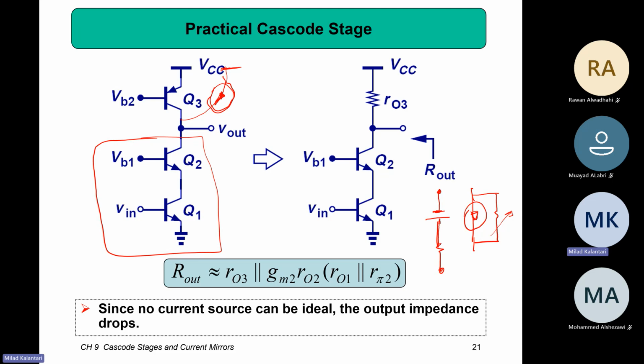So basically, when we are modeling the transistor, we see that the output side is like a current source, right? The model for the transistor has a junction diode at the base-emitter, but the outside is pretty much like a current source. It has the R out, but the R out is already large, so it's most likely a current source on the output side.